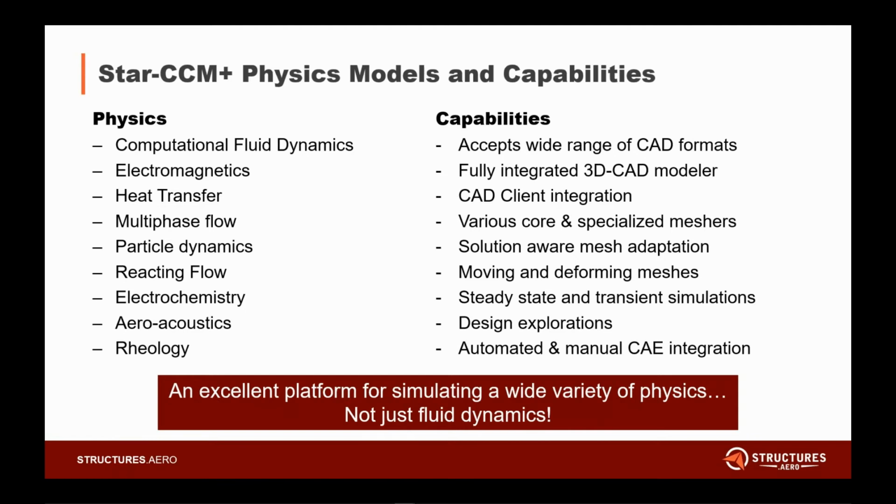Okay, moving along, there are various core meshers and specialized meshers, which I'll hit on probably in future webinars. You can mesh with different types of cells, like a triangular tetrahedron, a polyhedron, or a trimmed cell. And then there are different meshers which are specialized for meshing thin strips of material or directed tubes where you sweep along a profile. So it's kind of similar to a finite element mesh. It makes a lot of sense if you have a finite element background.